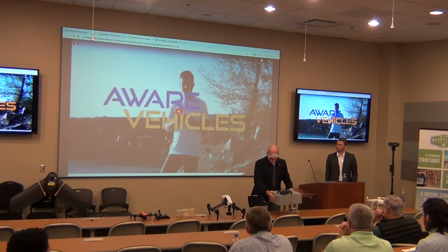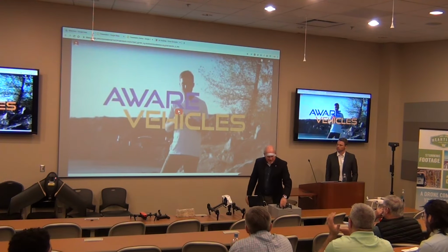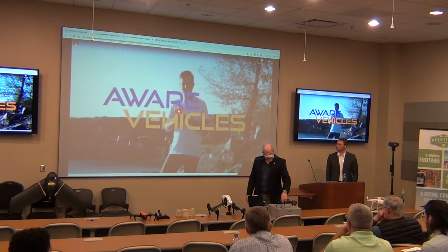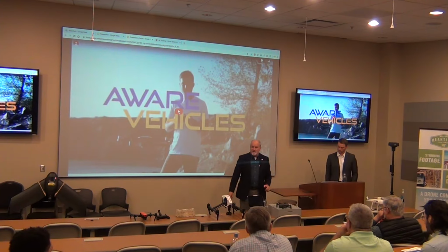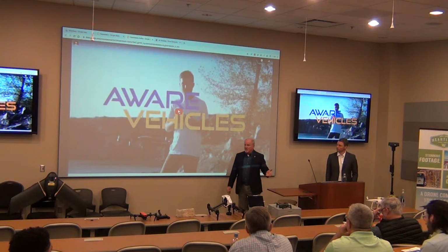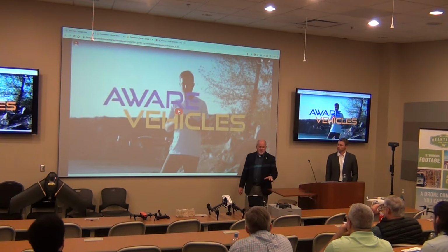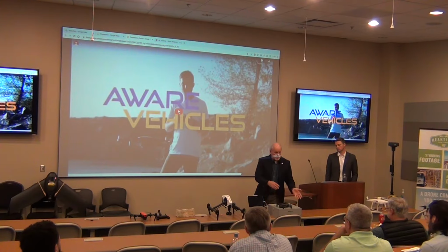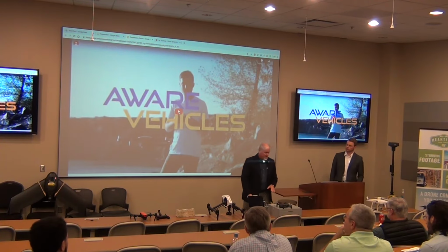This is a drone in a box, essentially. There's going to be a weatherproof box on your job site. The drone will take off, fly an automated mission, return to the box, land precisely on a QR code, attach itself magnetically to the docking station, and then discharge data, charge the battery, and be ready for the next mission. And in the meantime, inside of here, the information is being stitched into 3D models, point clouds, 360-degree panoramas, and it's being transmitted either by Wi-Fi or by cellular to the stakeholders. Real-time intelligence.